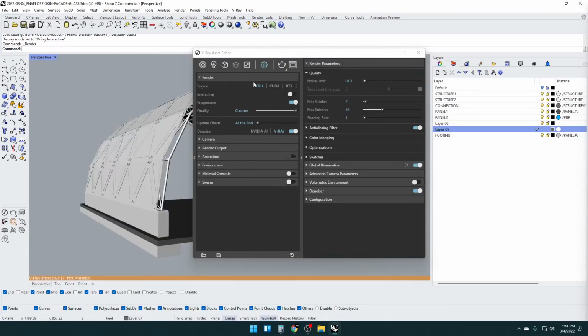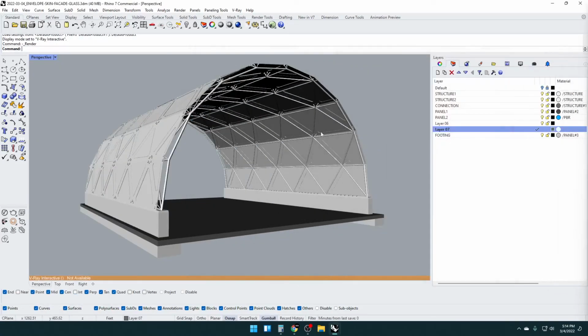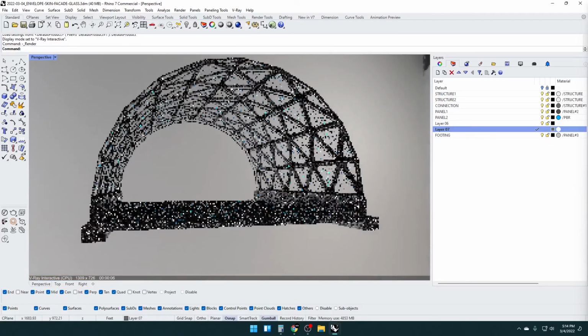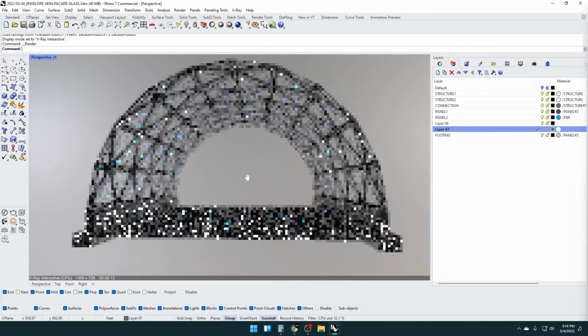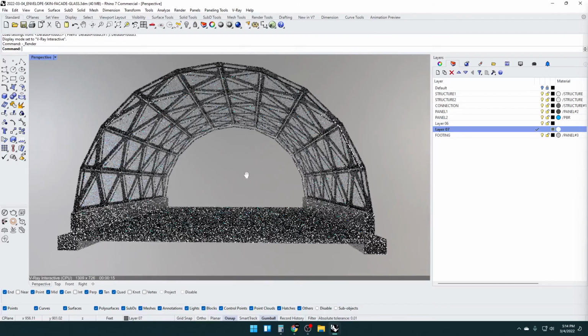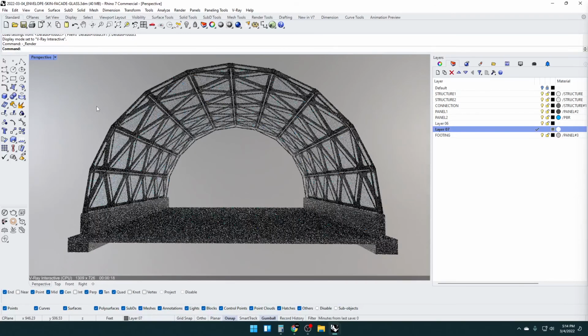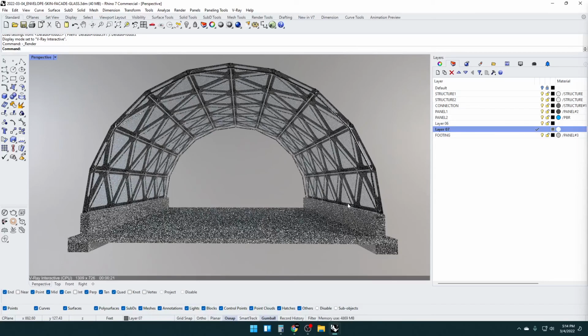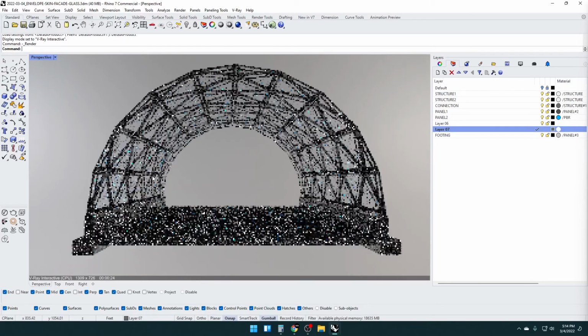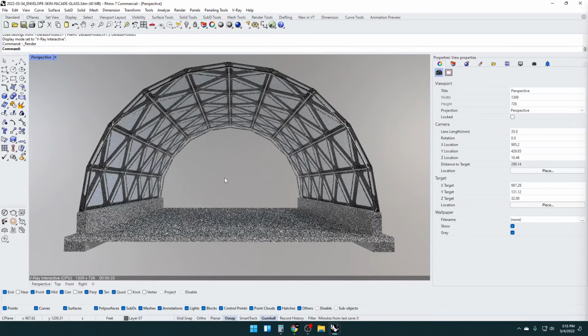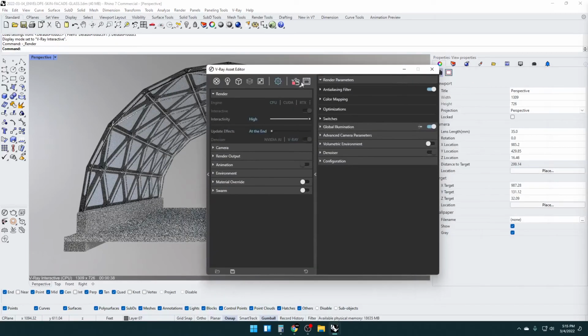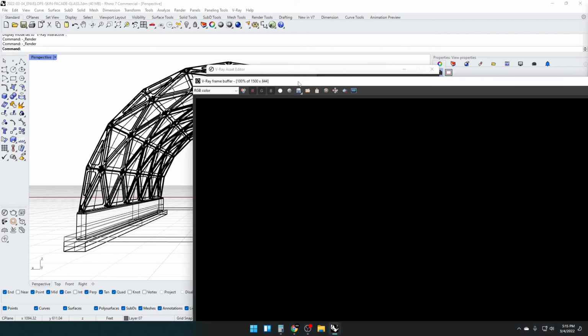And if I go here to V-Ray Interactive, I'll be able to see a preview of what my render is going to look like. And typically I want it to be facing the location of where the white background is, because this is a studio setup background. And I can change my aperture if I want to. So if this looks good, which I feel like it looks pretty good, I'll now go and disable that, and I'll go to regular render.